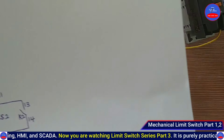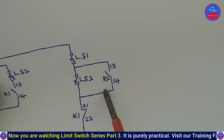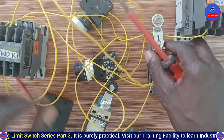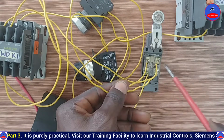And then the limit switch 2 open contact, we wired it in parallel with the contactor 2 open contact. Okay, so this is the limit switch 2, the top here.